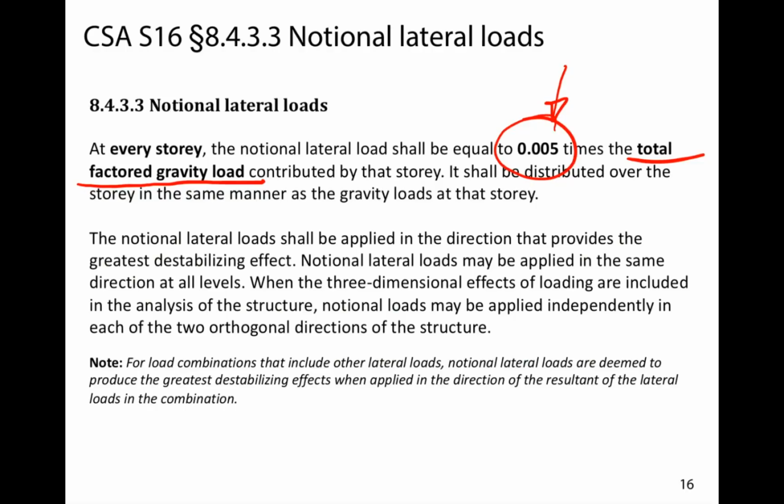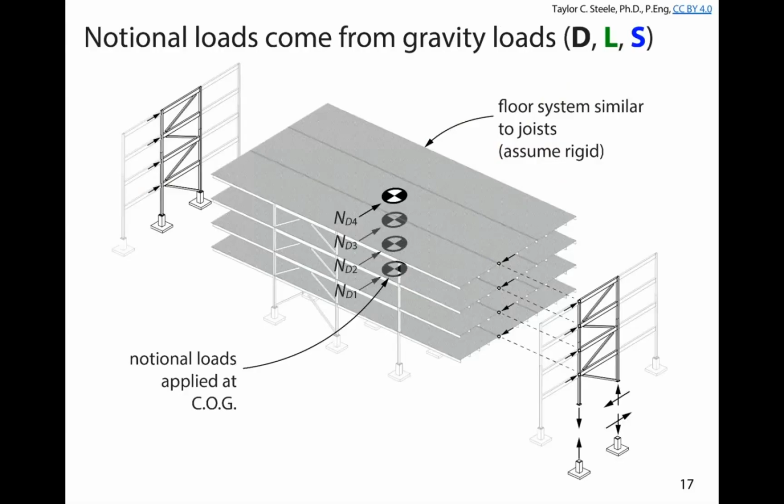I've got a couple different examples here in terms of how we would break them out into different lateral forces. For example, the first thing we're going to do is pick a gravity load. Maybe it's dead load, and we talked about dead loads in lecture 5. Probably we have a uniformly distributed dead load over the floor area, in our example structure, 4.8 kPa. Okay, so we're going to have 4.8 kPa uniformly distributed over the floor.